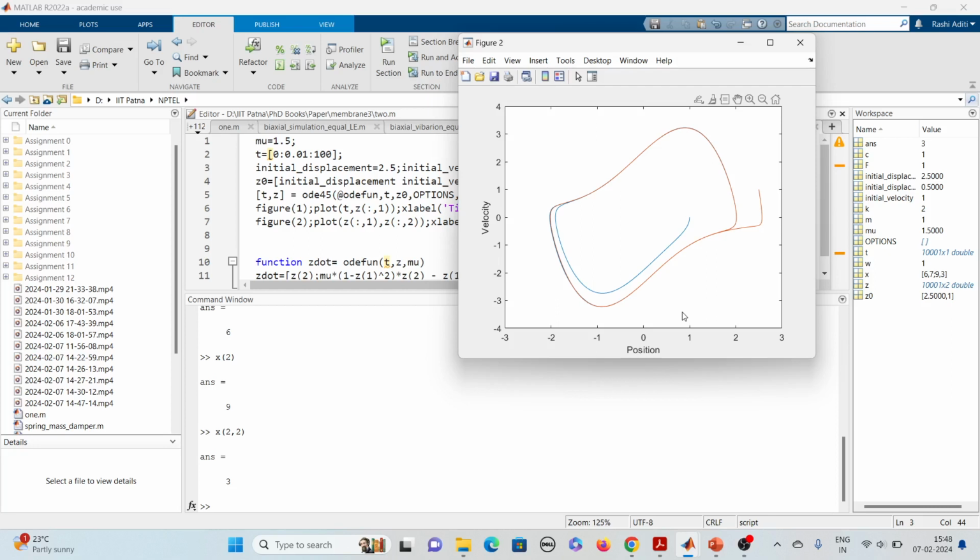And we are calling this a limit cycle because it is always following this particular closed trajectory. It is not going outside of this trajectory. It does not depend on the initial condition. If the initial condition is outside of this trajectory, it then also comes to follow this trajectory. If it is inside of this, then also it is going to follow the trajectory. This is not the case in a spring mass system, isn't it?